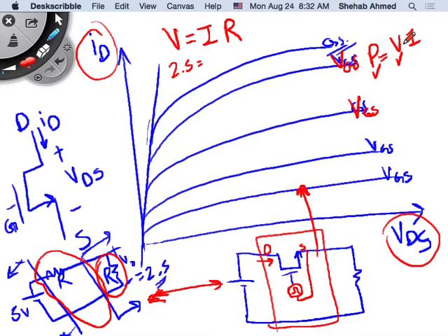When they build an electric car, they put in a big motor and a battery, right? They know the car's weight, they understand aerodynamics, they understand road-tire interaction, and based on that, they've designed their electrical system. So it's the same thing here. Because you know the power rating and the voltage rating of the load that you want to feed, you can calculate the current. If I know the current that's flowing in here, I can substitute that in this. Let's say it's 1 amp, right? And then I can calculate the corresponding resistance. So I was able to calculate the resistance that I need to stick in there.